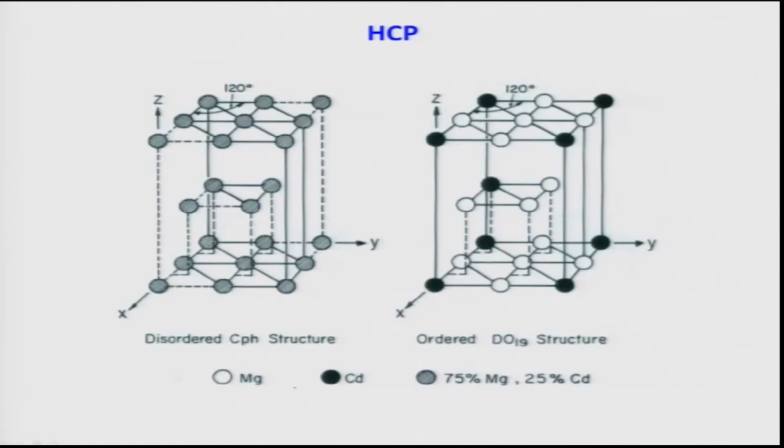The normal hexagonal close pack structure will have atoms sitting in the hexagonal layers and also the central atoms. Only look at the atoms sitting at the hexagonal layer. This is one hexagonal layer, okay, and obviously in the center of the hexagon there is also an atom, similarly here also, and the center also has another atom, and then you have 3 atoms which are not sitting in the lattice positions, sitting at the B position, A, B, A, like that we know.